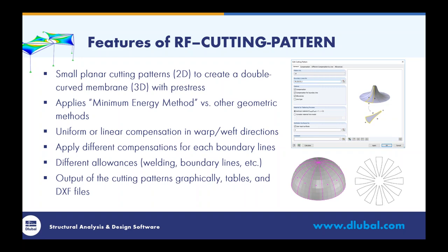What the program will do is it will press the mesh geometry of the curved surfaces into a plane using a press with frictionless press areas. This eventually results in our tension and compression stresses from this flattening process being in complete equilibrium. So that's the huge advantage of utilizing this minimum energy method.